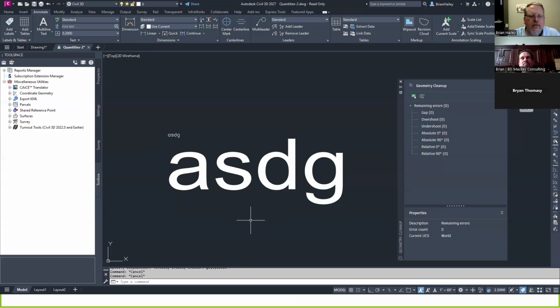Here at GEI, we just use Arial for everything. We don't use any other fonts. Try to use something standard straight out of Windows so that when you transfer it or somebody else opens the drawing, it's not going to ask for a translation font that it can't find.